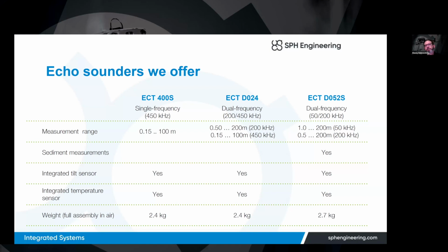And of course, if you want to achieve max possible precision in terms of sound speed, you can use separate devices called sound velocity profilers. But it is actually if you need to achieve extremely high precision. Normally, temperature of the water measured by a built-in sensor will be enough.